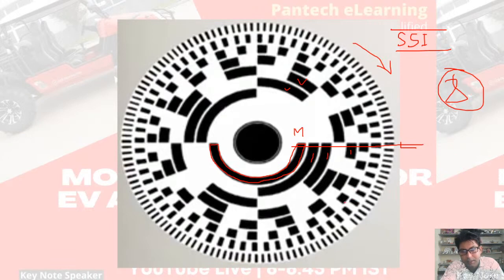Similarly, if it comes into a different position, say it is coming here, when it rotates and this line comes here, you will get 0 0 0 1 1 1 0. So in each and every position you will get a bit sequence. That bit sequence is transmitted through the SSI protocol, and we are able to read that data. This was basically what is inside the absolute encoder.